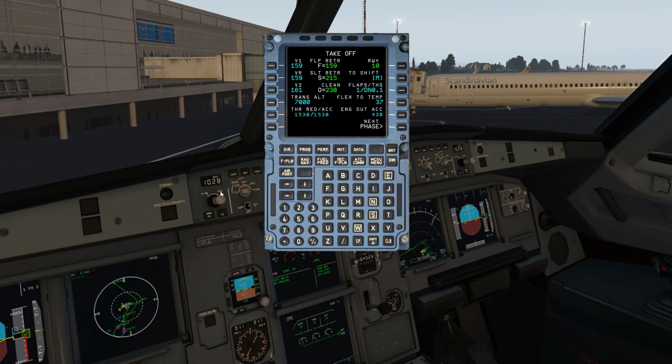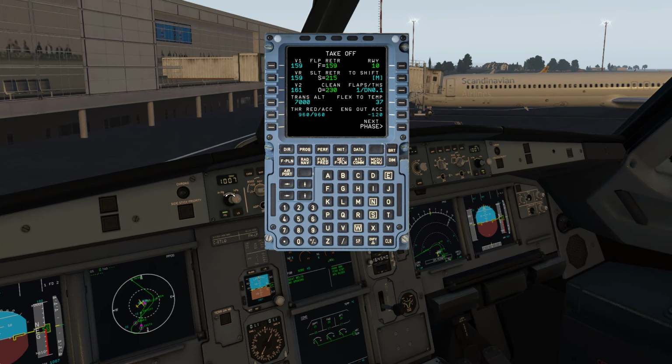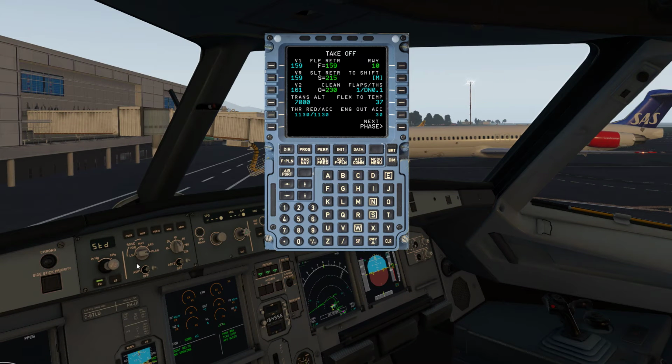Let's say someone starts in New York, where the air pressure is like 1033, and someone starts in France, and his QNH is like 1007. You want to give them altitudes to be at, but they both are on a completely different altitude, because they have different QNH. But if they both go on standard, they both have the same altitude shown on their display. So that's pretty much what QNH does.